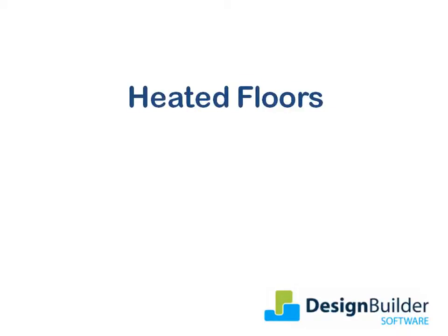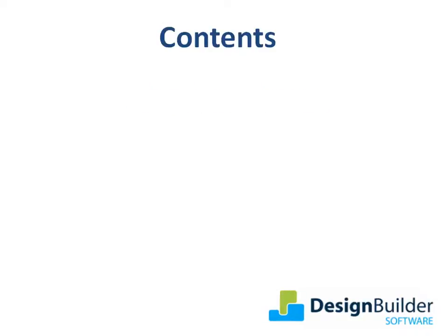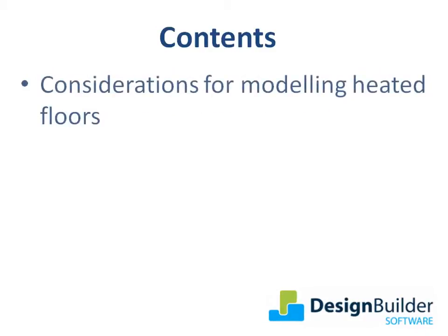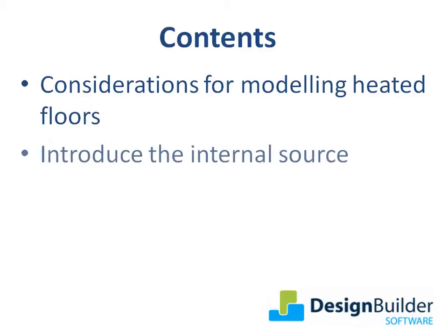In this tutorial, I'll introduce heated floors and show you how to model them in Designbuilder. During the tutorial, I'll discuss aspects of heated floors that you should understand before modeling them. I'll introduce the internal source, which enables you to provide heating or cooling via internal constructions such as floors and ceilings. I'll load the hot water heated floor template.